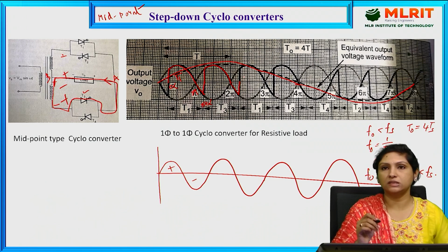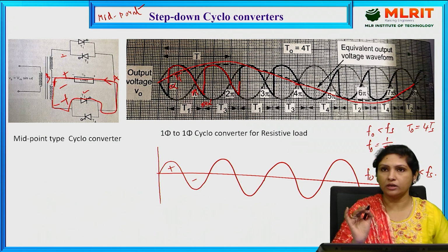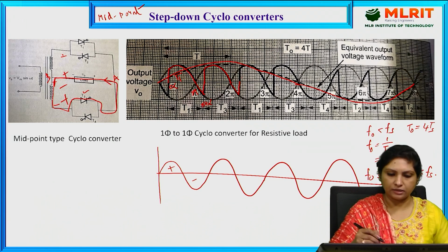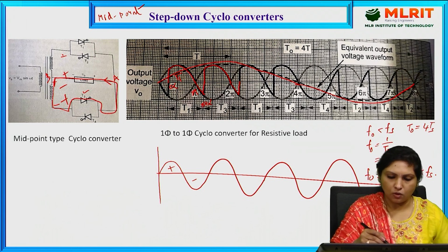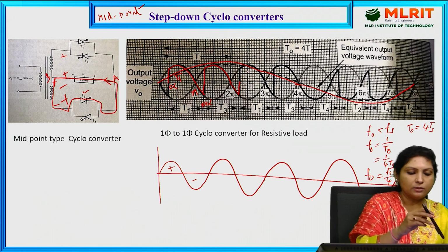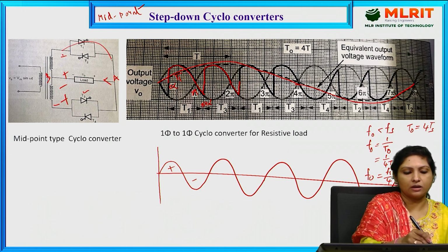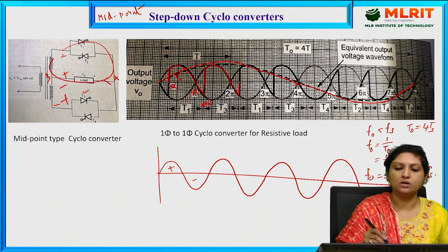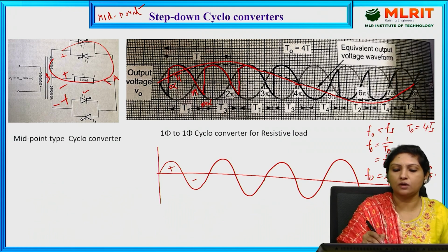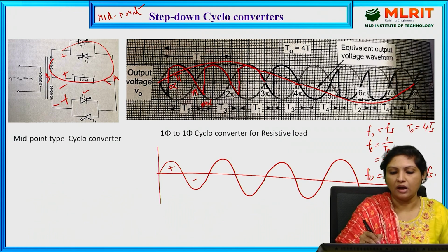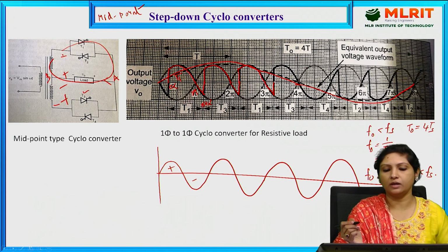Once it is dissipated and energy stored across the inductor is 0, at that instant, again during the positive half cycle, we provide the triggering pulse for thyristor 1 such that thyristor 1 conducts current through the load from A to B. So our positive half cycle of the output voltage is controlled, and it is conducting beyond 3 pi because of the presence of the inductor.